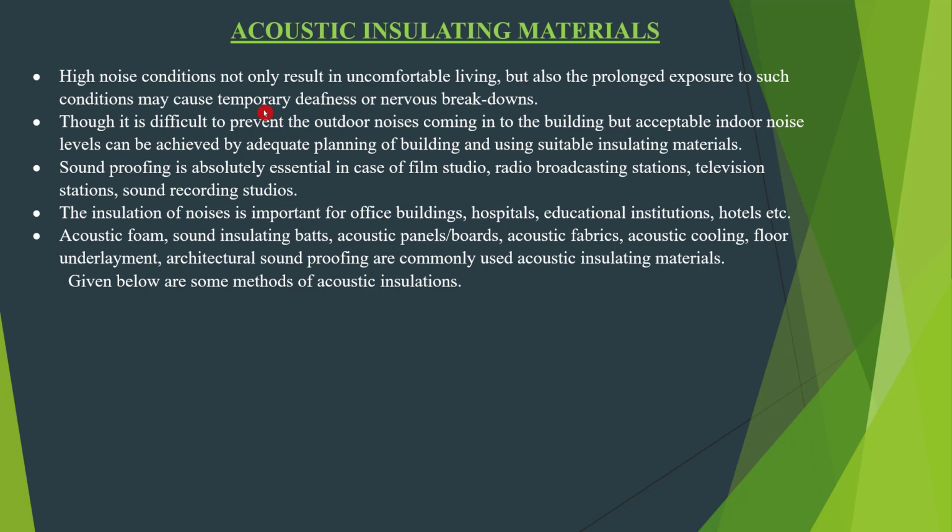It may cause temporary deafness or nervous breakdowns. Though it is difficult to prevent the outdoor noises coming into the building, acceptable indoor noise levels can be achieved by the adequate planning of building and using suitable insulating materials. So this is our aim. And soundproofing is very important in the case of film studio, radio, broadcasting station, television, etc. Because even a small voice will affect their program or their work.